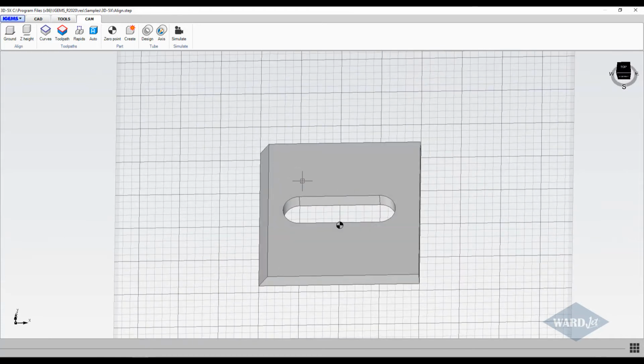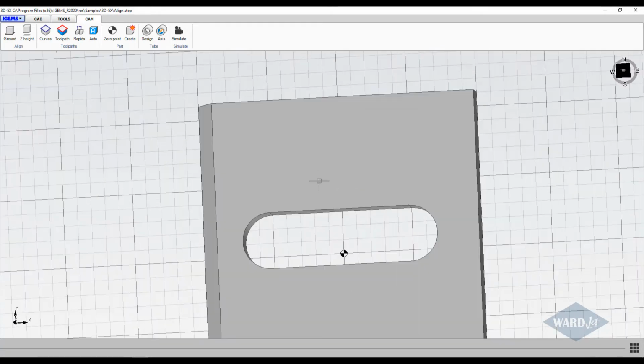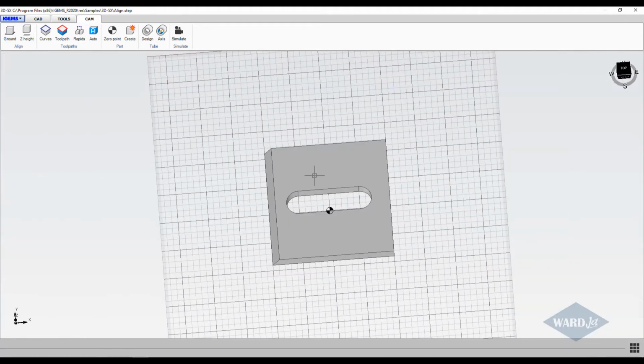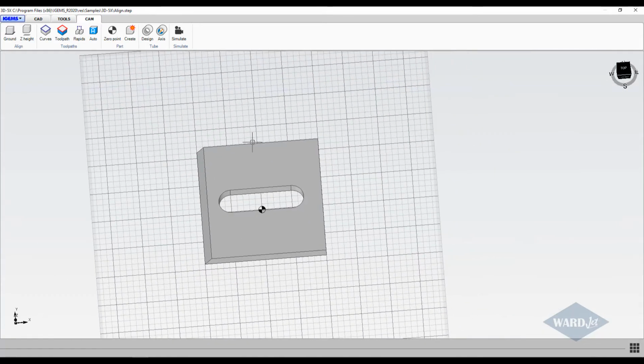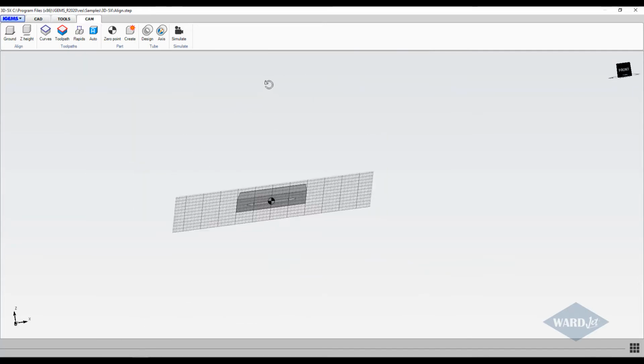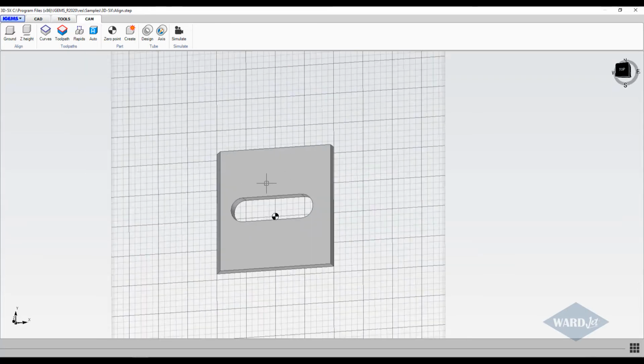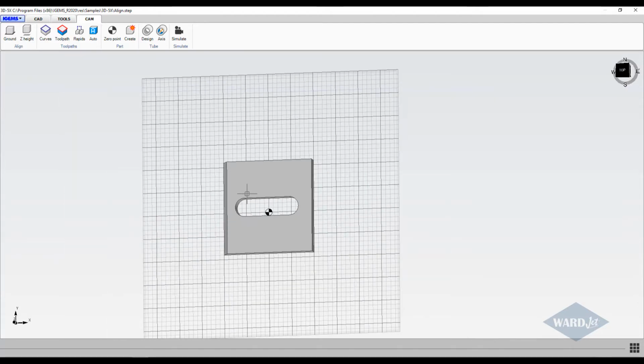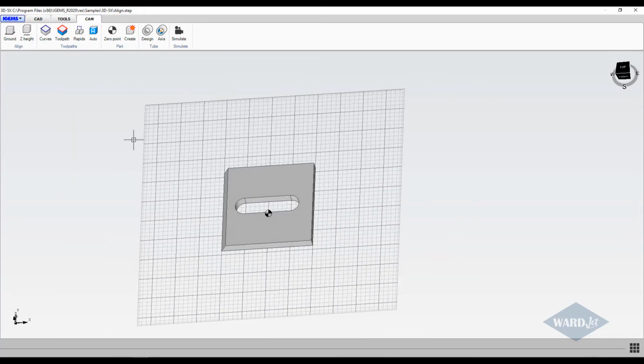So we've got a bevel cut on this side and then 3 straight edges, and the slot is also straight. You can also spin this around the Z-axis depending on how you want this oriented on the table, or you could do that back in the 2D world. This orientation here looks fine, so we'll just go ahead and start picking some edges.